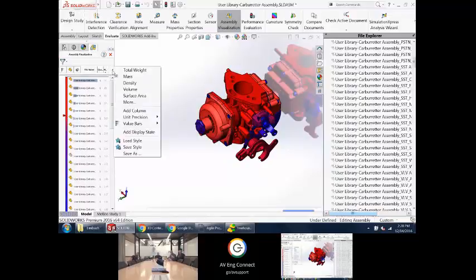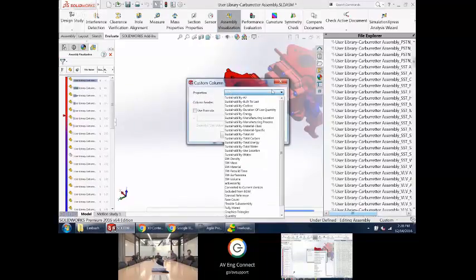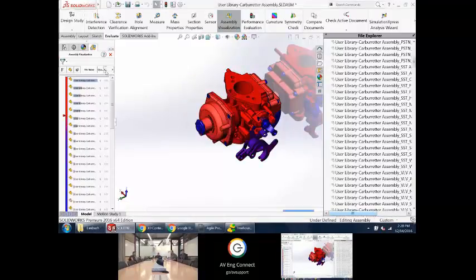You can also sort by all kinds of stuff. I can sort by surface, by area, or I can even do it by SolidWorks rebuild time. So this shows me how long it takes: 3 seconds to build that part, 1 second to build that part. These are all adding up, right? So when you open up a full assembly, especially if you open it up full weight, it's got to bring in all those parts, rebuild them, and take a look at where they go. It's got all that information in there.